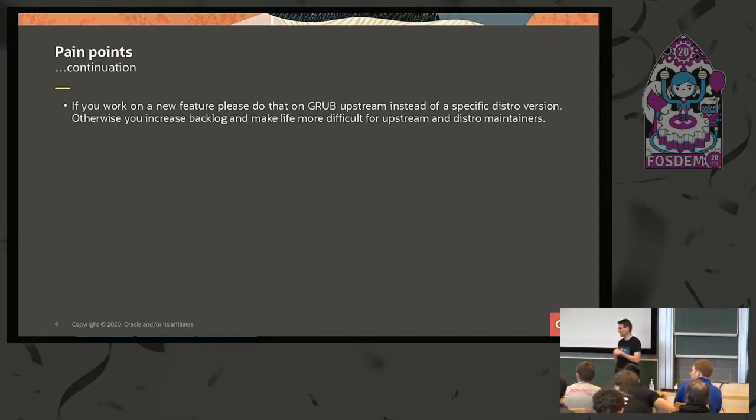You mentioned that on new AP systems you try to access the TPM check for some security reasons. So is this something that, for instance, in U-Boot should also be implemented as a protocol that you would want to consume? The question was that I mentioned during my presentation that there is a TPM implementation in the GRUB which uses UEFI features. And the question is, do I suggest that U-Boot should provide these UEFI calls to have a TPM?